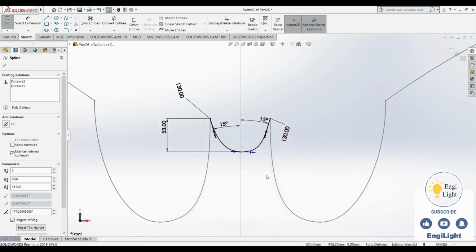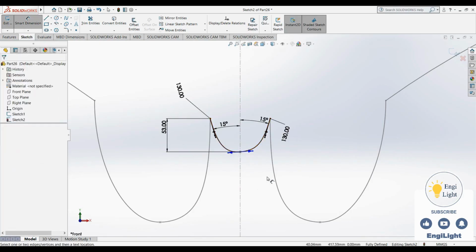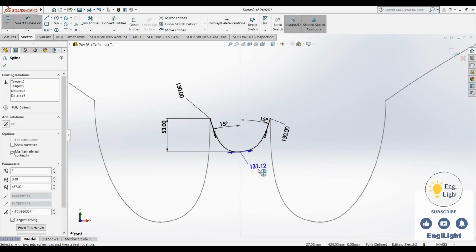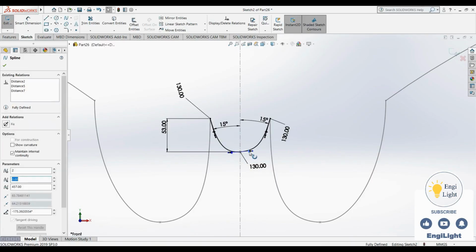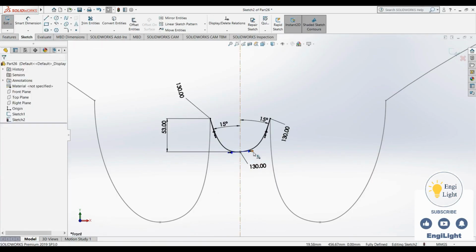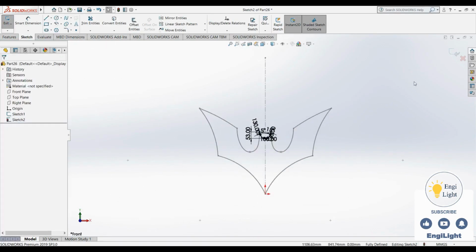One's at 79 millimeters. I just pull it down towards 65 millimeters. Then, I set the total handle length to 130 millimeters, and I align it horizontally. And that completes the sketch.